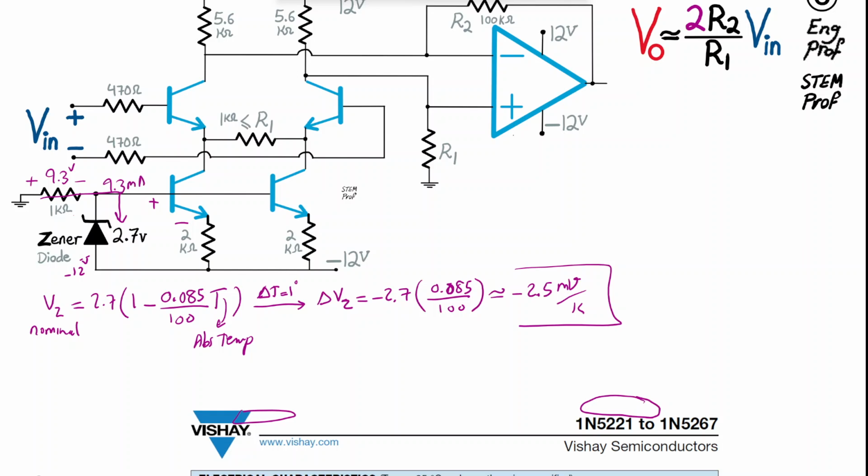Okay, that's perfectly fine. So that is a very good, healthy current supply for the Zener diode to make sure it is far from the knee point of the Zener diode and is perfectly on. So that's a good thing.